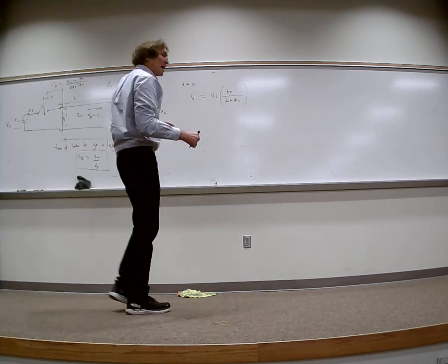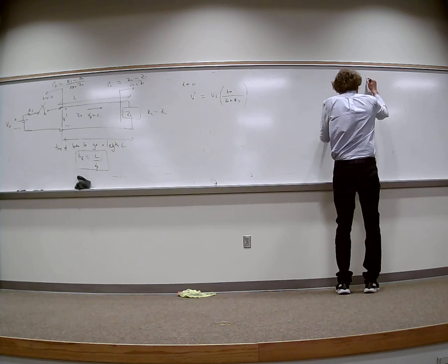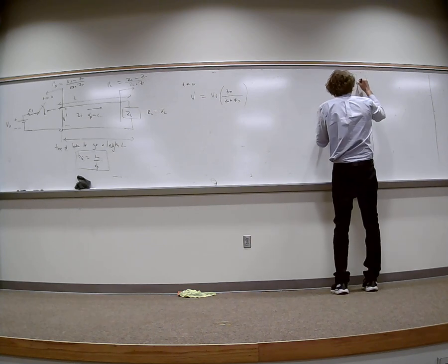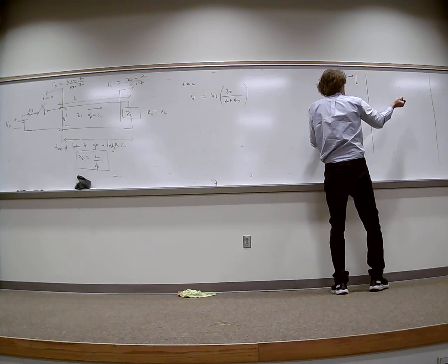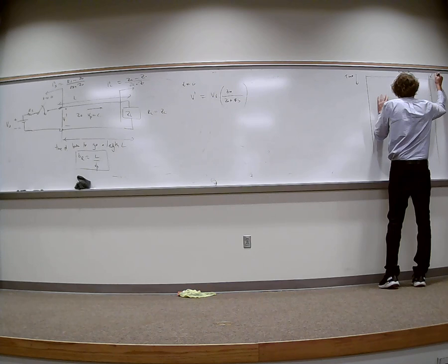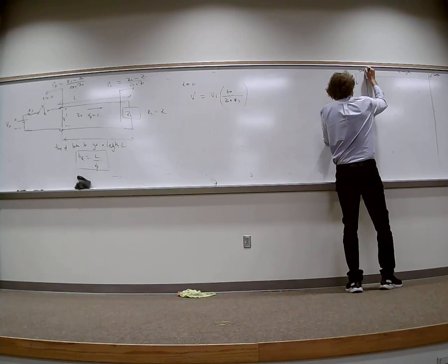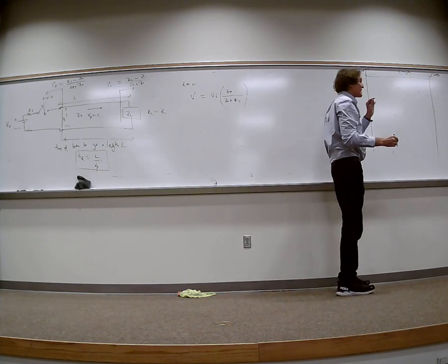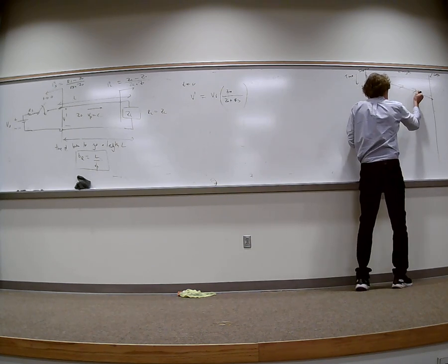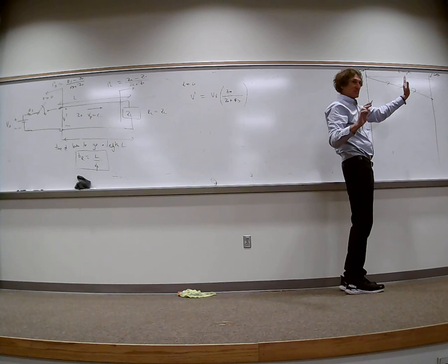Okay. Now for the bounce diagram. Pay attention to this. We take a look at time on this axis, and then this is the length of the line, and here's where the load is, and here is the source. And we do this. We start out, we say, as time progresses, we're going to have a wave front that's going to have a value V prime moving this way. You're just going to have to bear with me on this. I'll get to what all this means in a second.